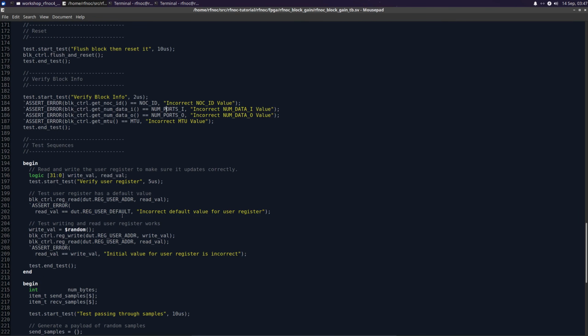That way we know that we're talking to NoC shell, that a clock isn't left unhooked, or a reset hooked up incorrectly leaving things in reset, or that NoC shell didn't get generated properly. This is a nice test right here.